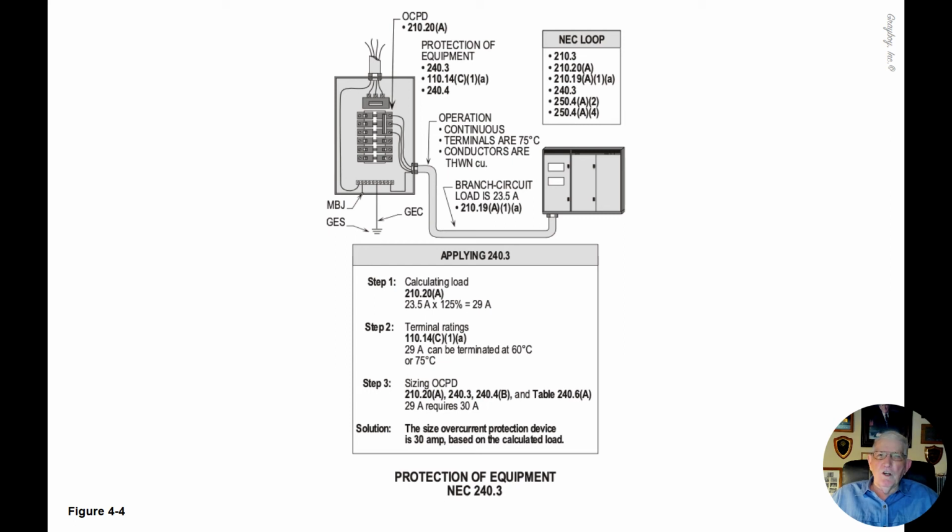Remember, a 100 amp or less device has 60 degrees C terminals unless marked 60/75 or 75. Any overcurrent protection device or equipment terminal, lug and so forth, that's over 100 amp, then the terminal ratings are automatically 75 degrees C.